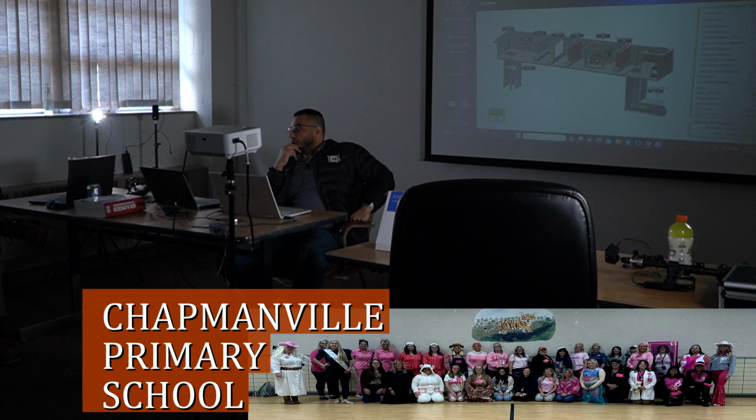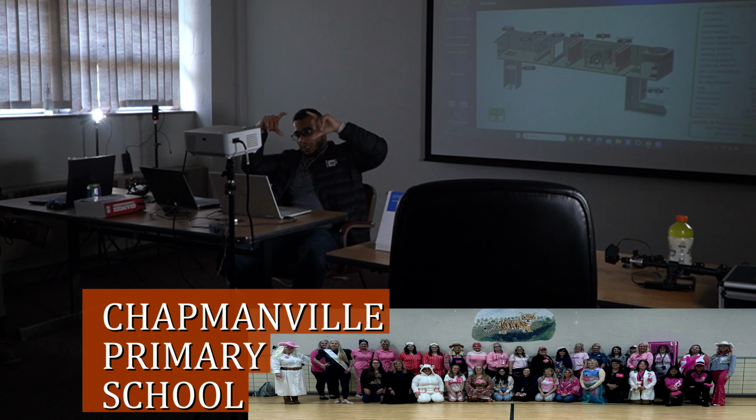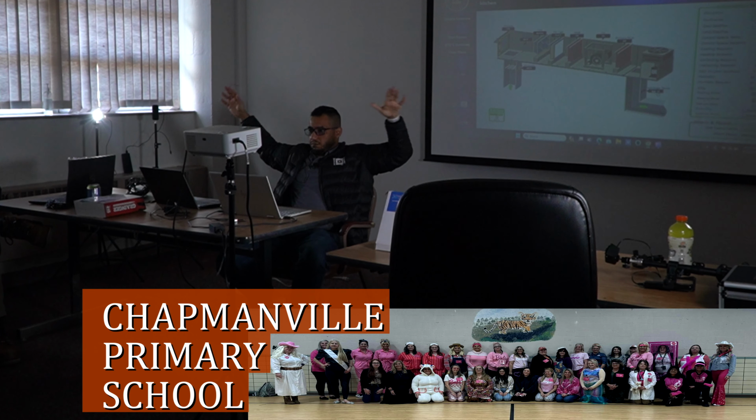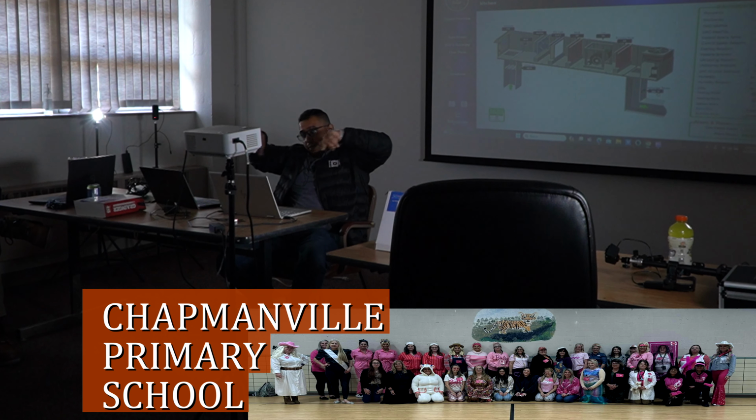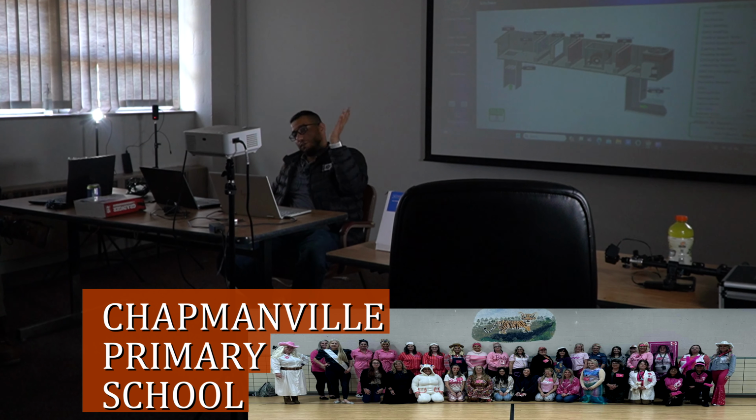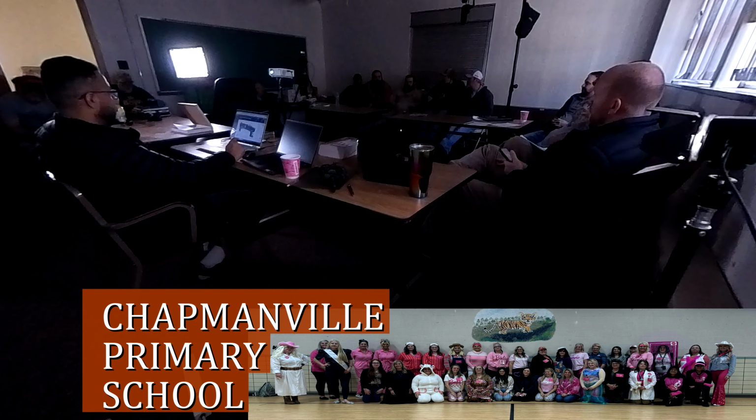After we end, probably with Logan Middle next week, that way we put the last control we have there. But Chapman Primary, for example, this one is an RSTP, which is basically a ring topology. And that means any equipment going to shut off is not going to affect the others, because the bus of the communication runs both ways to the end. So if something in the middle has been shut down, you should still be able to see what's going on through it, left and right.